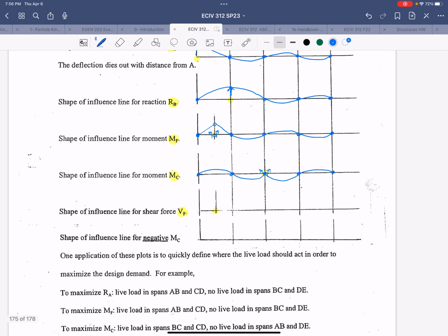And then if we want to draw the influence line for a shear at F, we add that roller guide to F and force it through a unit displacement, right side up, left side down to total 1 unit, but we don't really have to worry about the values. We're just drawing the shape. All the support conditions must be met. So we draw curved line on the right side, and then similar to this guy up here, the segment from A to F is vertically unstable on its own, so that portion will just have a straight line.